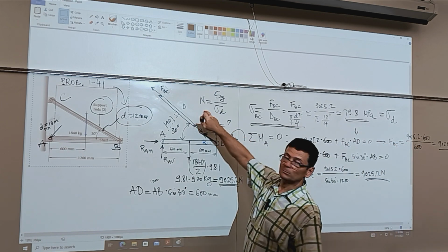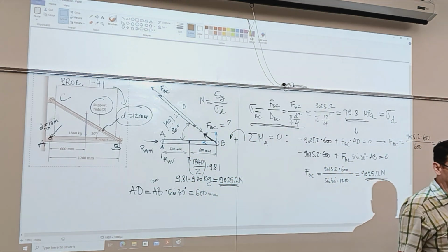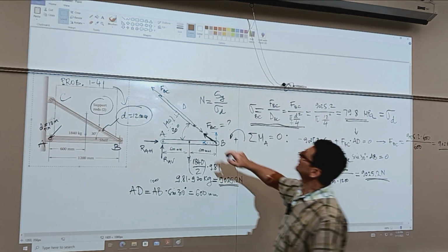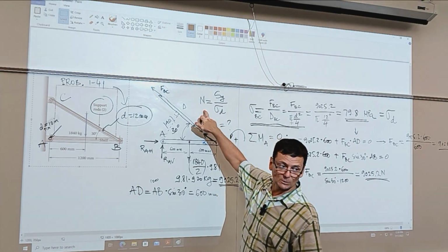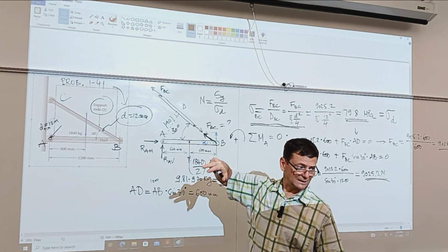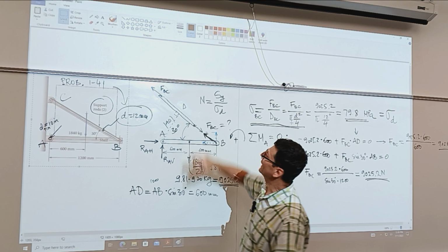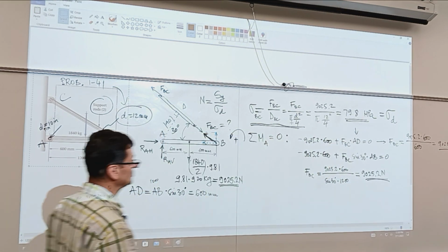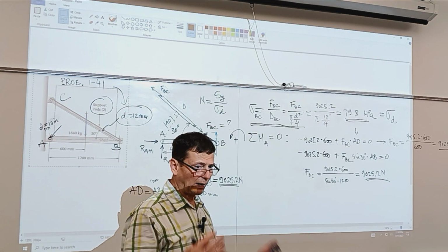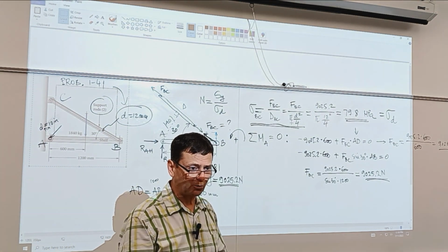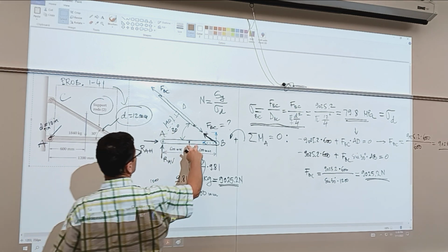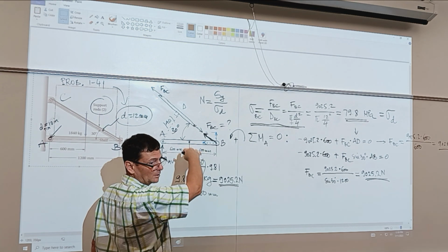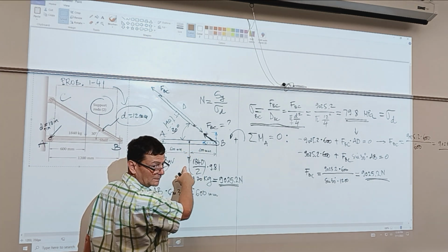And you want this number to be, depending on the application, for a building-like structure, code experience tells us that a number of 1.6, 1.7 would be okay. Mechanical engineers work with numbers like 2, 2.5. Why? Again, I'm anticipating, it is a chapter 2 subject. So why have design factors? To account for uncertainties in load. This may get overloaded, accidentally somebody may climb on top of the crate and increase this over the anticipated value.